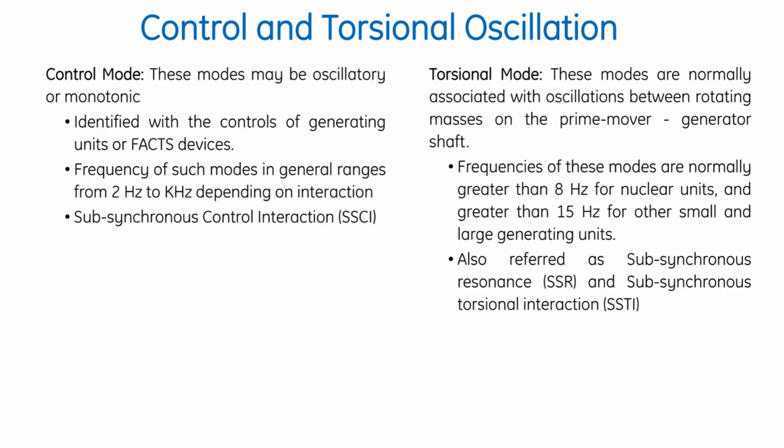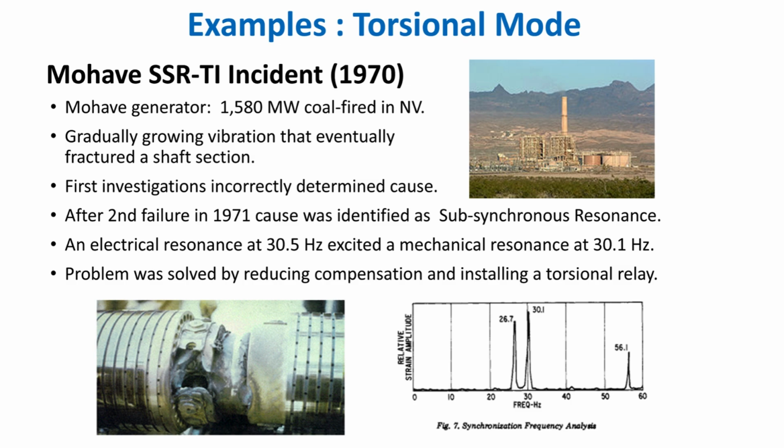Wow. And what causes that twisting? It's usually excited by electrical events on the grid, particularly things like subsynchronous resonance or interactions with certain types of power electronics or series capacitors. But the oscillation itself is the physical shaft flexing. That sounds damaging. Extremely damaging. These are very high-frequency oscillations, often 10 hertz or even much higher, and they can cause severe fatigue damage to the multi-million-dollar shaft system very quickly. So torsional modes are less about immediate grid-wide stability, and more about protecting that specific, expensive piece of rotating machinery from mechanical failure. Still critical, but a different kind of problem than inter-area instability.